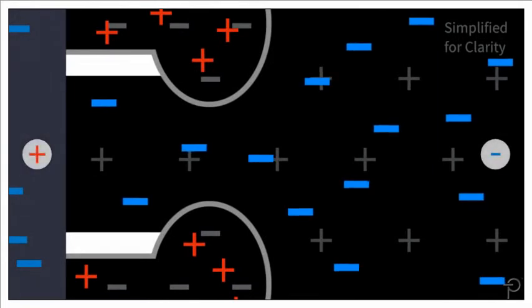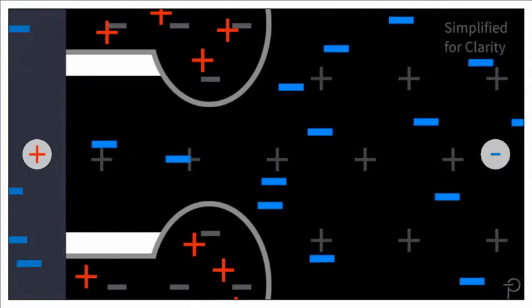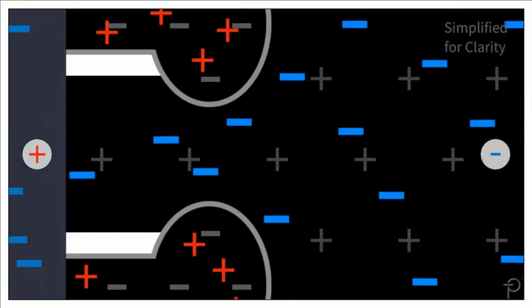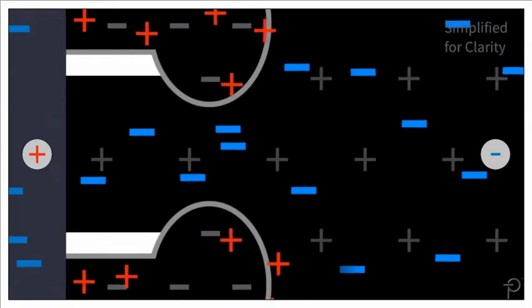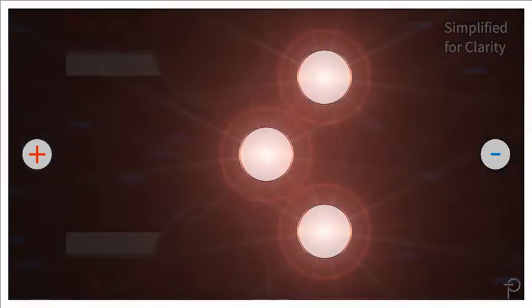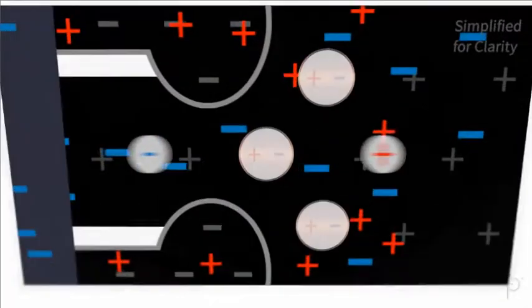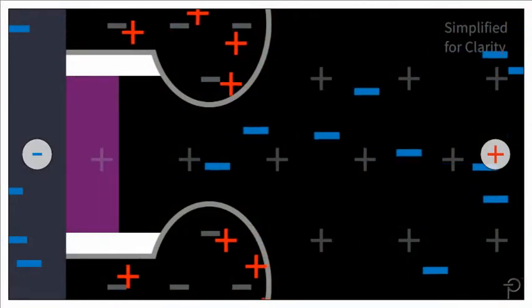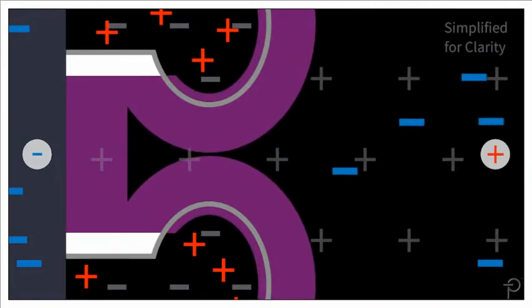When the diode is forward biased, the Schottky junctions conduct immediately, and electrons flow into the channels between the P-wells. As the diode conducts more and more current, the voltage in the channels begins to increase, until it becomes so large the P-wells start to inject holes as well. These holes recombine with the electrons at the channel entrances, directing all carriers through the P-wells. When the diode is reverse biased, it enjoys both the fast reverse recovery of the Schottky sections and low minority carrier injection losses from the PIN effect, providing an extremely fast, low-loss recovery.